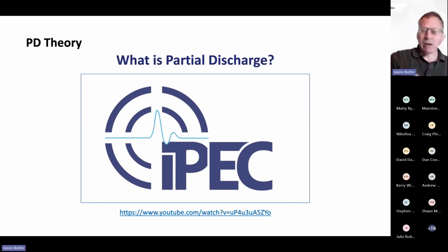Okay, there we go. A little video just to bring it to life a bit. Again, PD gives you that indication of deterioration, whether it be from damage or installation or from contamination. And you're doing it non-intrusively, so you're doing it outside of the high voltage enclosure, which allows you to have that separation between you and the conductors. Right, let's move on.